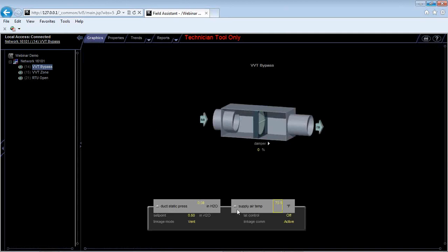The reason you have a supply temperature on here is to prevent short cycling of air with VVT systems. The location of these, you don't want to be bringing really hot air back to the unit too fast, or really cold air, because you could potentially freeze a coil or burn something up here. So if you don't have a good bypass placement, there's a logic built into this system to start to modulate that damper closed if your temperature is getting too high. You're bypassing too high air or too low air to protect your rooftop and your air source.